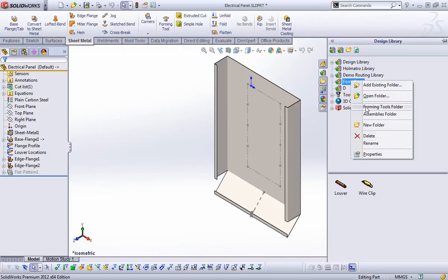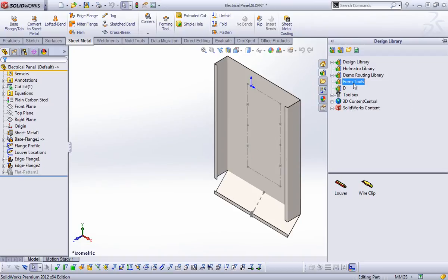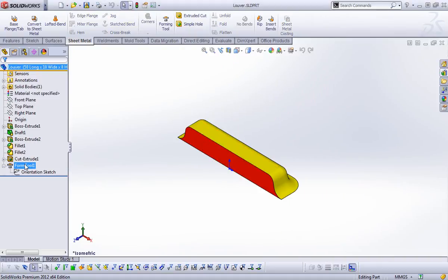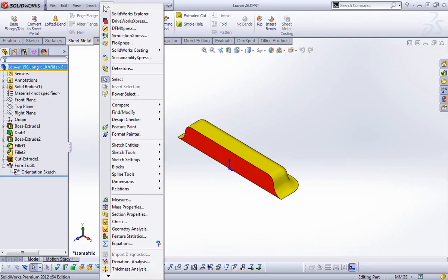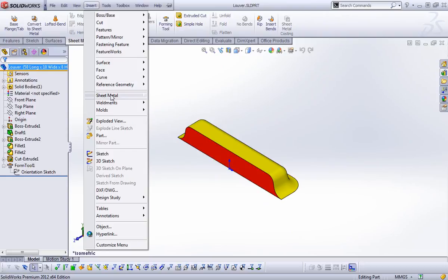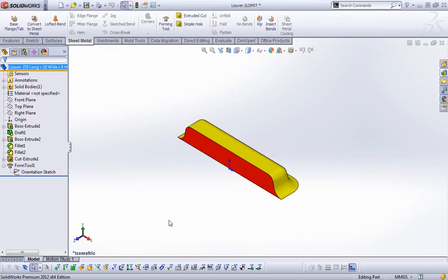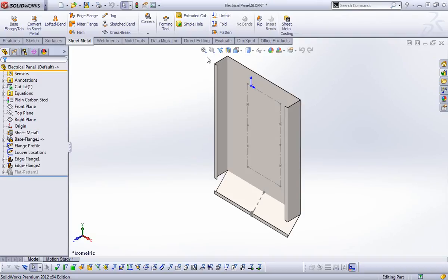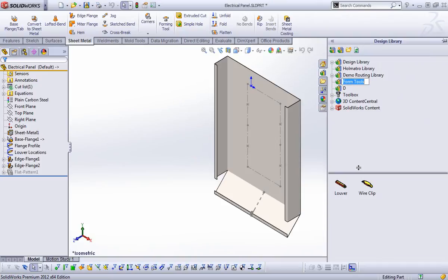So what makes it work is the ability for it to recognize the forming tool features. If I open this up, you can see that the forming tool feature has been applied. To do that, you would just create your model and then create a forming tool. Whenever you create the forming tool feature, it prompts you for some information about how a forming tool works, or the specified faces. Again, you can hit the help file for that if you need more information, or give us a call.